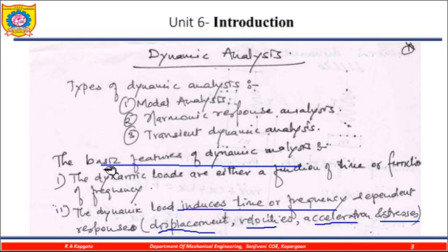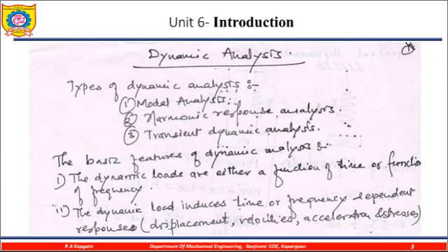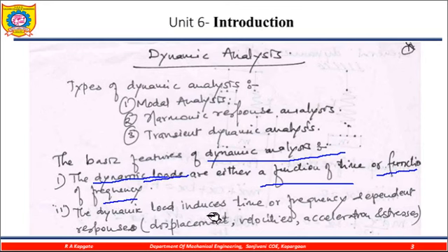So in dynamic analysis we consider dynamic loads, which are functions of time as well as frequency, and which induce responses called displacement, velocities, acceleration or stresses. That is called dynamic analysis.